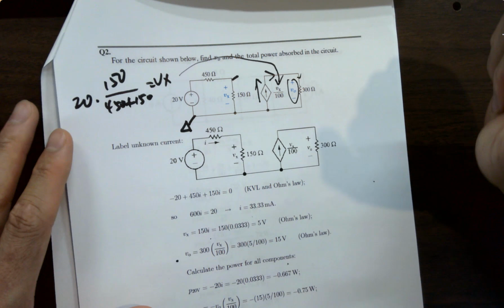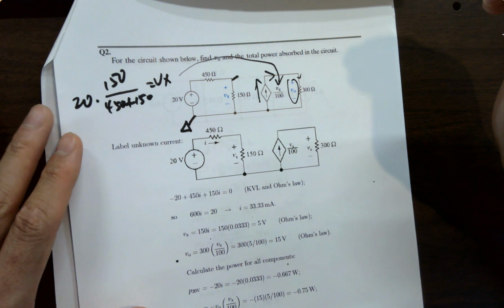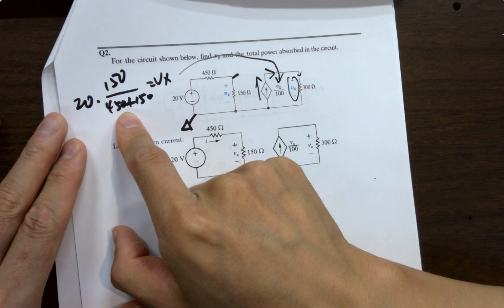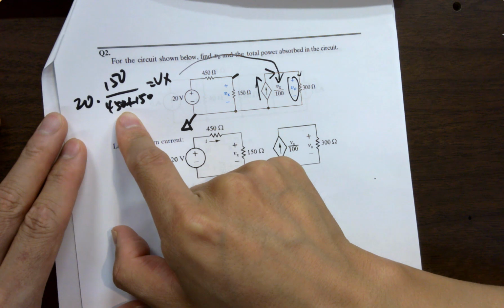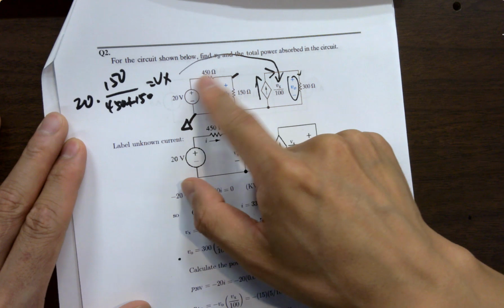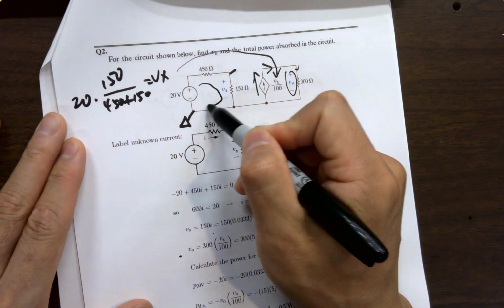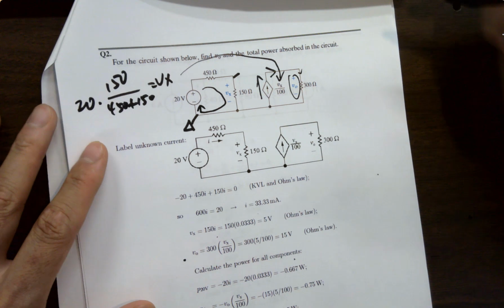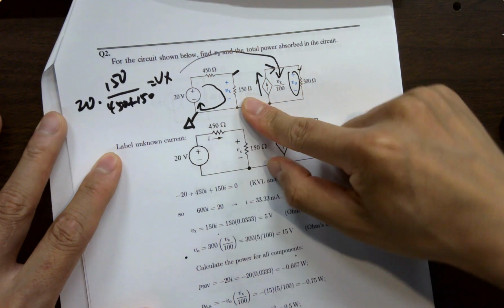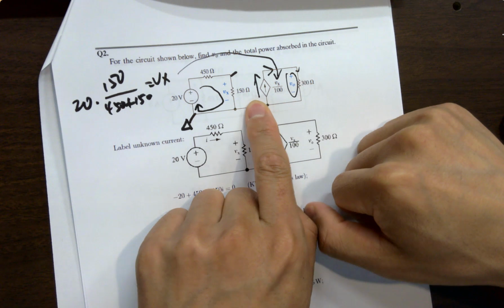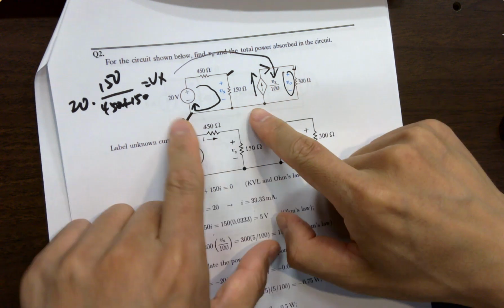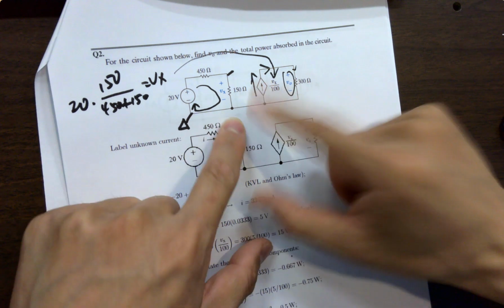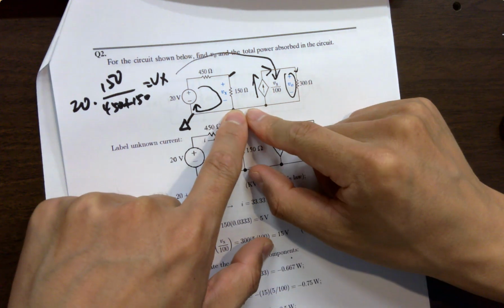Did you combine the 450 ohms and the 150 ohms and then treat them as being in parallel? They're not in parallel, they're in series. It's one loop. This is the ground. It's flowing back to the cathode. Why are they in parallel? You got scared by this wire, right? Always look at this wire. It's just the ground, just the reference. You just melt it and it becomes one node, one piece of metal.